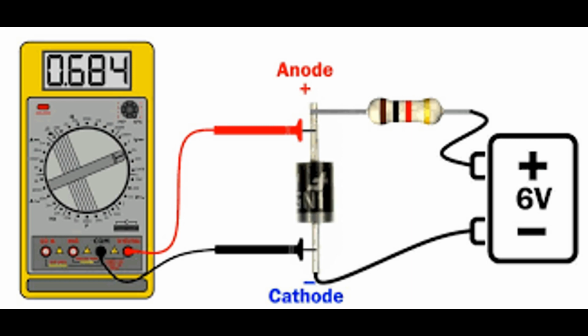Voltage shifting, also known as voltage level shifting, is a technique used to change the voltage level of a signal from one voltage reference level to another. It is commonly employed in electronic circuits when interfacing components or systems that operate at different voltage levels. Voltage shifting is essential to ensure compatibility and proper signal communication between different parts of a circuit.